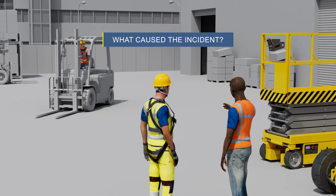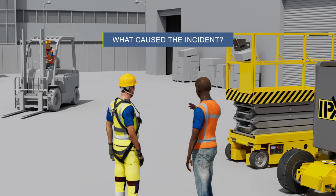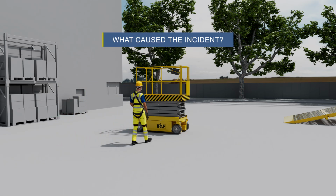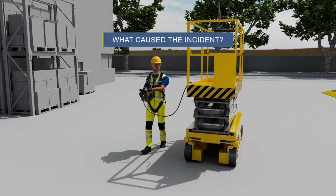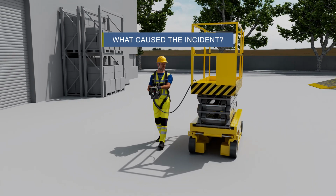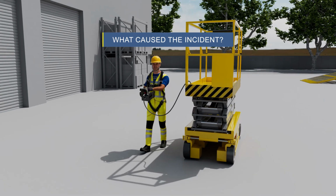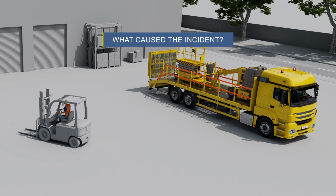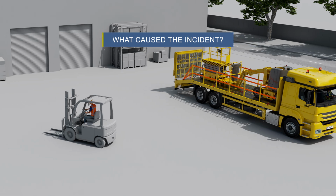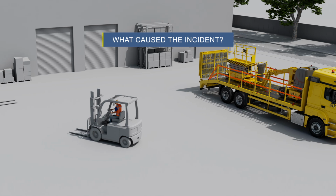Now we will examine the lessons learnt from the incident. The mobile elevating work platform involved was a 3A mobile vertical lift, a narrow deck scissor lift. These machines may be fitted with detachable controls and can be operated in pedestrian mode. This is only intended for situations where operating from the platform would be unsafe, such as a risk of crushing from low overhead ceilings or steel beams, or uneven ground causing a risk of overturning.